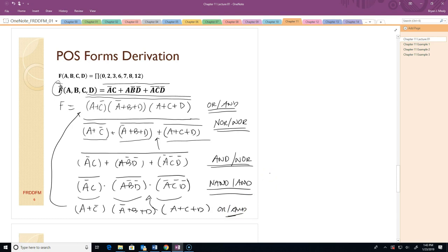Okay, so once again, these were 8 standard forms. 2 of them are really popular: OR AND OR, NAND NAND, NOR. They're all generated from SOP equations and POS equations. And all I'm doing is double overbarring these and grinding through with De Morgan's theorem. It works. I don't have to memorize anything other than the fact I have to put an overbar over from the starting point.